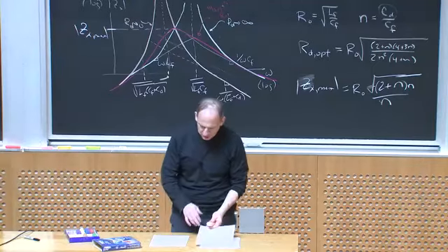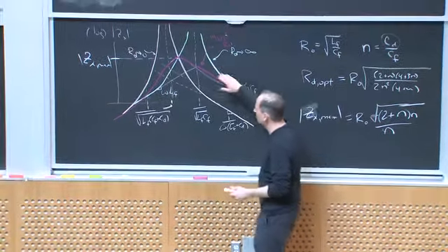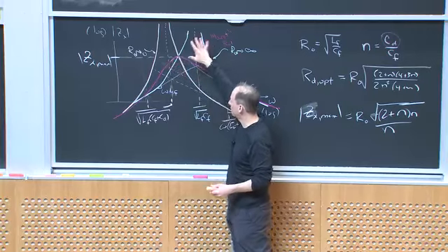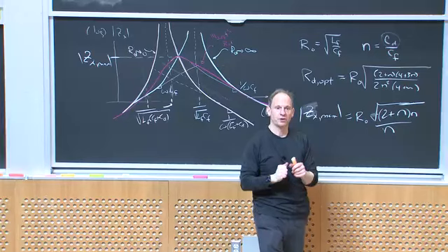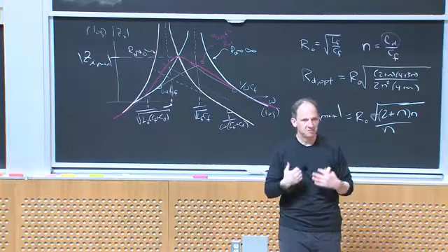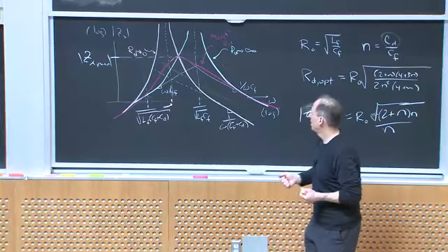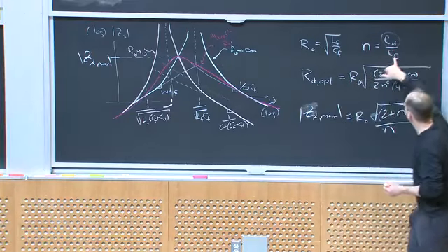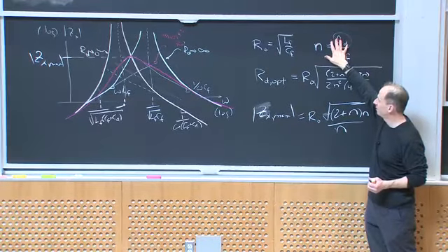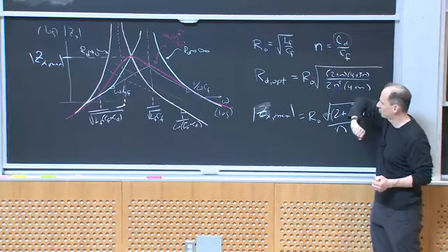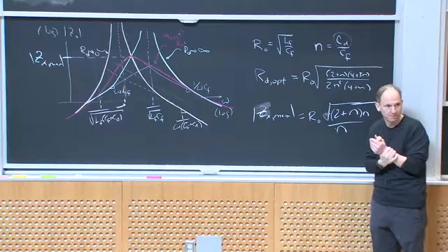All right, so what we're going to do is ask how well damped I want this to be. First of all, design my filter LF and CF to attenuate the ripple frequency. Then I'll ask how well damped I need this to be down at the cutoff. And I will pick N, the ratio of CD over CF, to be big enough, and then out of this we'll drop what filter damping resistor I need, and then we have a filter.